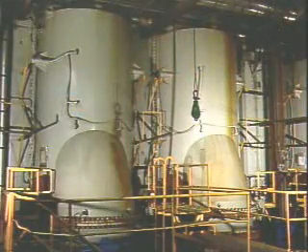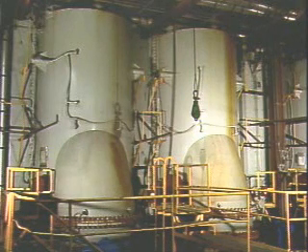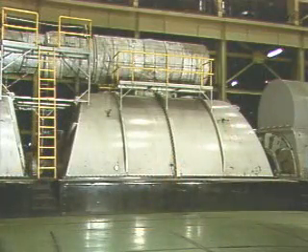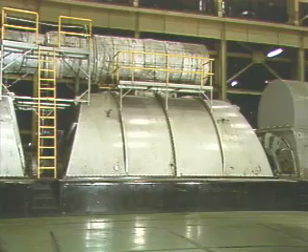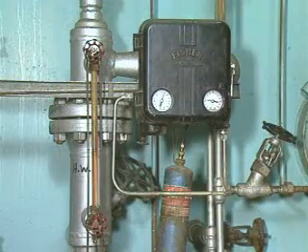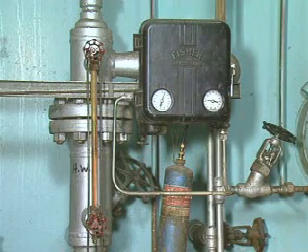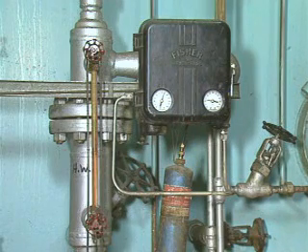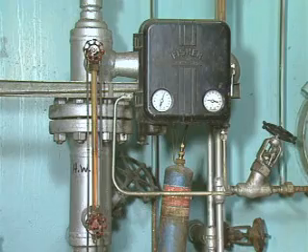This condition could flood the lower sections of the tubes in the main condenser and reduce the condenser's overall condensing ability. In an extreme case, water from the main condenser could get up into the turbine and destroy its moving blades. A level control loop is used to maintain the correct level of condensate in the hot well. Basically, condensate flow out of the hot well is decreased if the level falls below a preset minimum, and increased if the level exceeds a preset maximum.